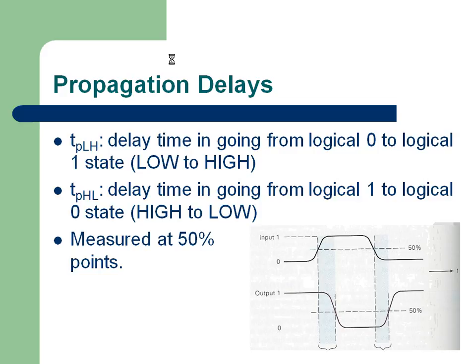You understand? Now, let us assume that this particular gate's fan out is 10. Fan out is 10 in the sense that it can deliver a maximum of 10 milliamperes. If there are 10 devices, each one will get only 1 milliampere, and each one's input capacitance is 10 picofarad. So all of them will take T1 amount of time to reach the input logic level. But if there is only one gate, then this gate will be able to switch faster. Got it?